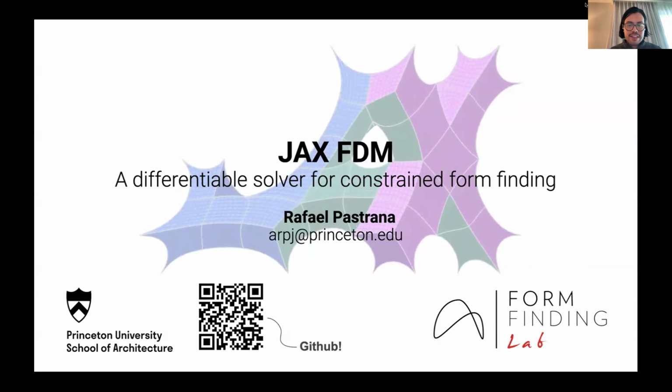So while we could go around and build a bunch of physical hanging chain models to generate these structurally efficient shapes, today we have access to a plethora of numerical form finding methods that allow us to compute these geometries in a computer. Perhaps the most popular or the most consolidated numerical form finding method here is the force density method, or FDM. I'm sure that more than one person in the audience has heard or even worked with it.